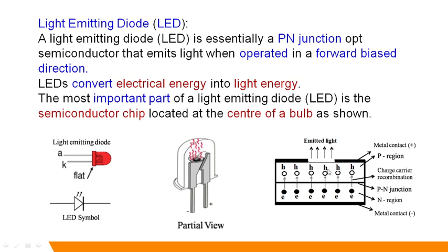This is the junction, and this is the P type semiconductor. Over the metal substrate, the N type semiconductor is grown. Above that, the P type semiconductor is deposited by the method of diffusion.